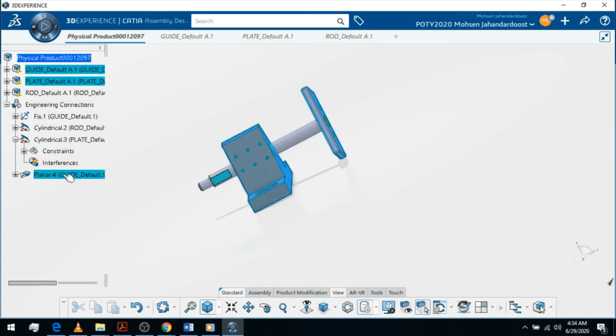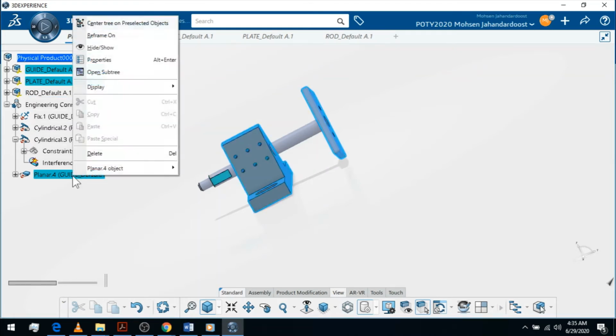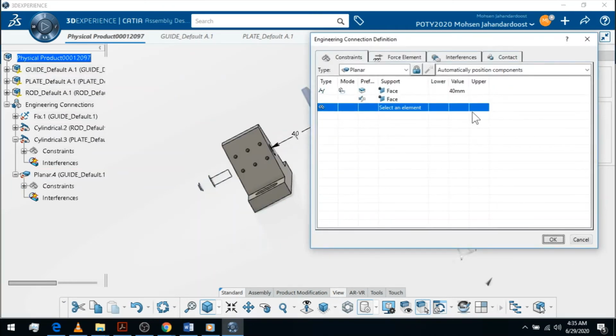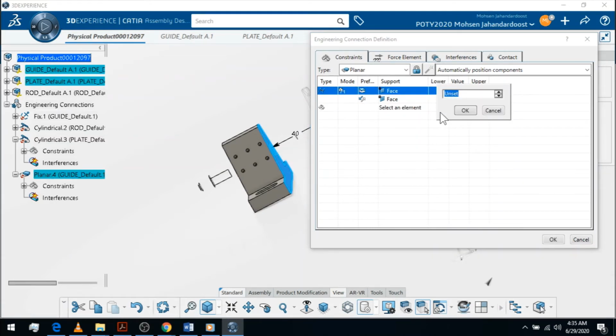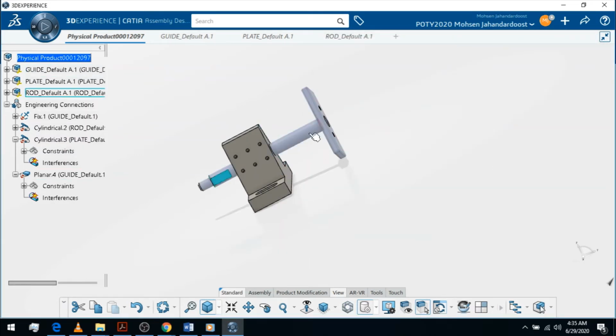Now if I want to put a bracket for the movement of this part, let's say that this bar moves inside my base in the bracket of 15 millimeter to 45 millimeter. So I can go and edit my offset here, and this time I double click on the lower value, and in the lower value I put 15 millimeter, and in the upper value I put 45, for example, and I will say that it sits down at 40 millimeter. So at the first view it sits down at 40 millimeter, but I have the option to move the part between 15 and 45 millimeters.